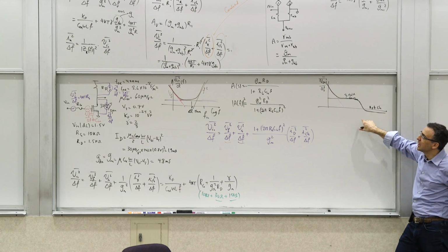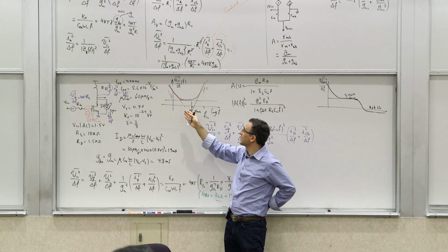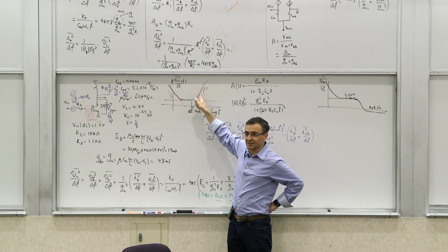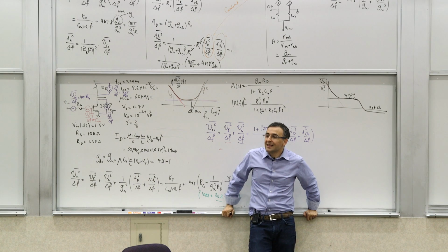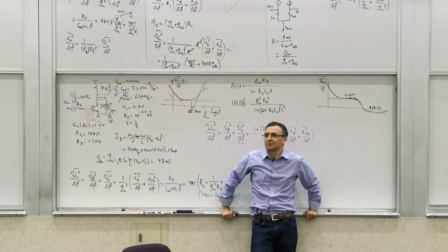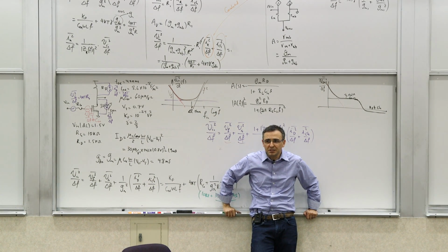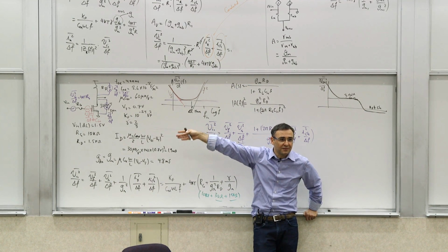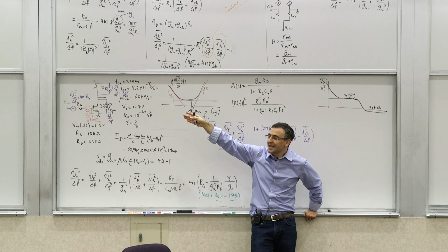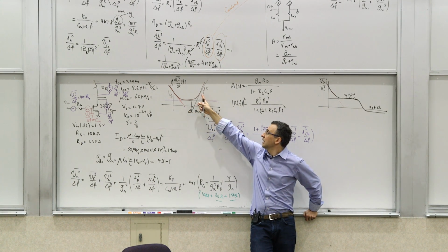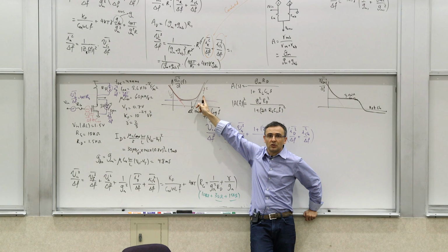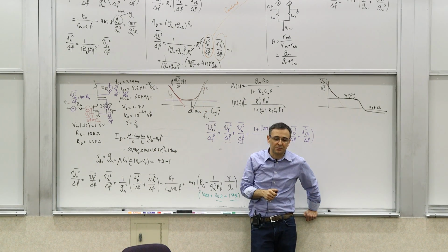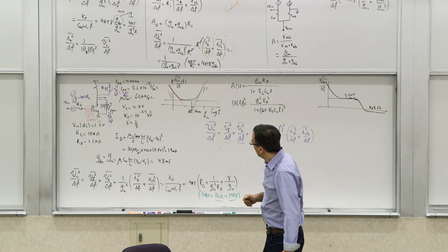But now, a lot of times when you look at amplifiers, when you do characterization, if you look at the data sheet of a transistor, if it's low noise, you will see plots like this. Again, this increase that you will see at high frequencies is a fictitious increase. It's not there. You cannot go and measure that, but it's a relevant one. Because if you had a signal of a certain value, it would result in a lot smaller signal-to-noise ratio at high frequencies compared to low frequencies. So that's what that means. Okay? All right.